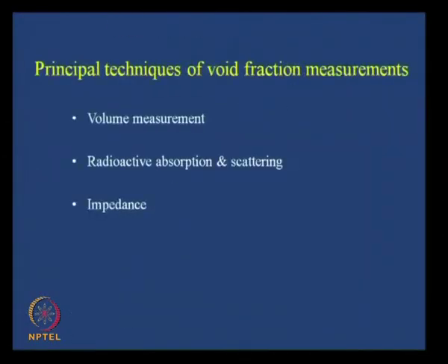Okay. So, there are different techniques of measuring the void fraction. They can broadly be categorized into volume measurement. Simply by some process, you very directly measure the volume which is occupied by phase 1 and the volume which is occupied by phase 2. Naturally, this is the most direct method and the most standard method. Definitely, there are some problems in using it in industries, due to which other measurements have come up, but remember one thing, everything has to be calibrated with this volume measurement value before they can be used for further applications, right. So, therefore, the one thing is direct volume measurement.